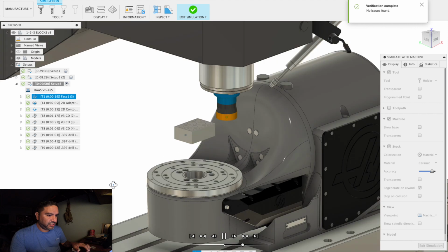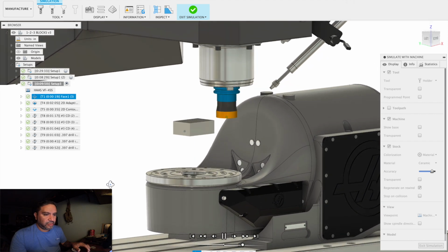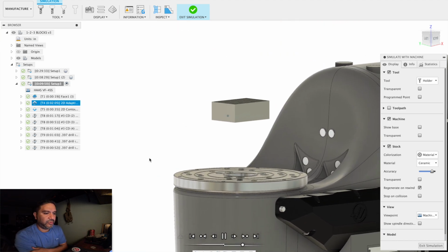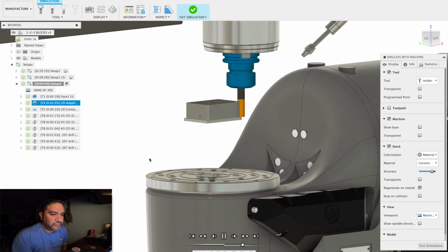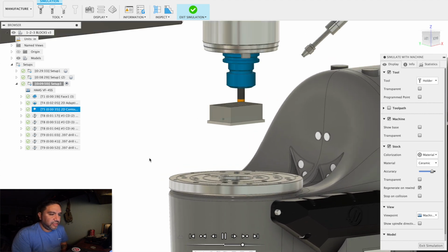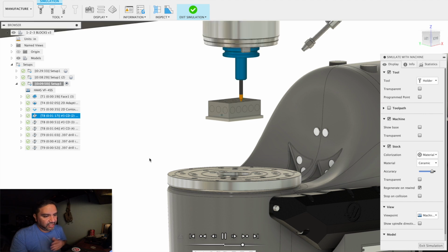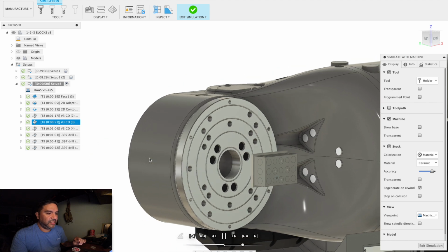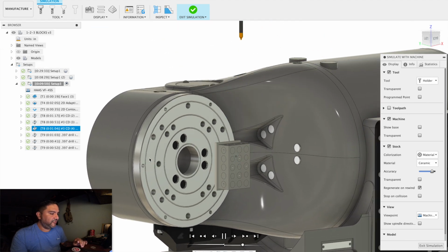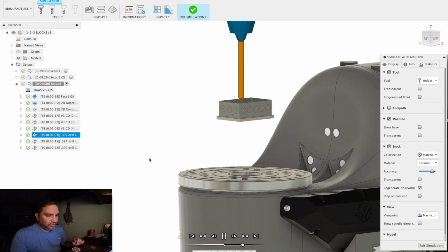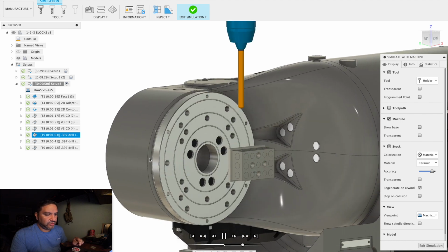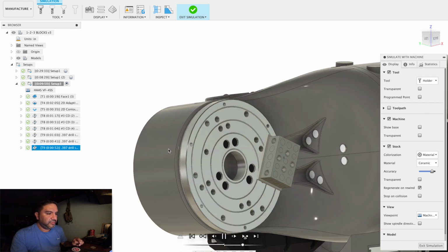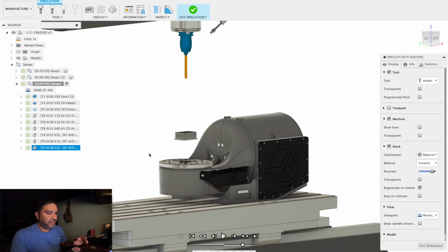Let's scroll a little bit so we can see what's going on. And here we have the Z, the head stationary, and the part moves around. That was roughing. Finishing the exterior. Machining the top. You see the head tilt. Drill 3 holes. And it turned again. Still at 90. Now we reset for the drill. Drill the top, drill the side, 2 holes, turn around, drill 3 holes. Machine goes back home, Y-axis comes to the front for the operator, and you're done.